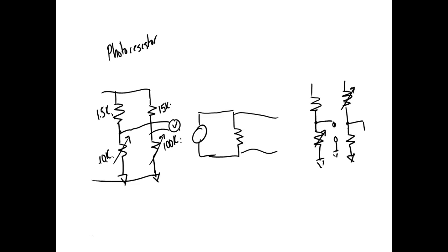Now while we do that, we had the same indicator that would run on different scales. They'd have different weigh bridges. They would have different load cells, right? You understand? So we had to do it that way. So we calibrated the actual indicator to what the load cells gave us. But we do use a Wheatstone bridge, and we'll show you why when we get there. We use Wheatstone bridges a lot. In fact, there's one on the test.